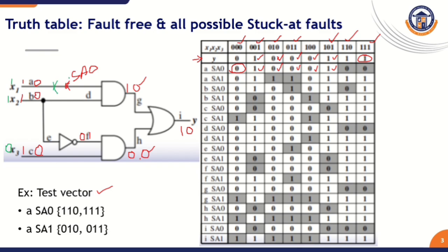But this line is affected by stuck at 0. So when we are applying the combination here, this line is affected by stuck at 0. This line always generates only logic 0, whatever inputs we are giving here. At that time it generates only logic 0. So based on this concept it generates the output and propagates it. That is, here the value is now considered as 0 1.